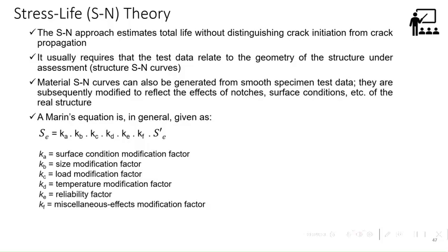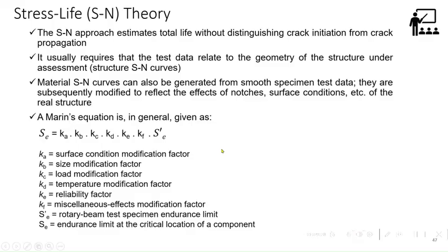You have a domestic project. If you want to do it, obviously, engineering judgment can be used, or you have to generate data to justify that. Whereas this Se I was telling you about now is related to the specimen endurance limit generated, and this is the actual endurance limit. I will show you an example of how important it is to consider this, otherwise you will go wrong.